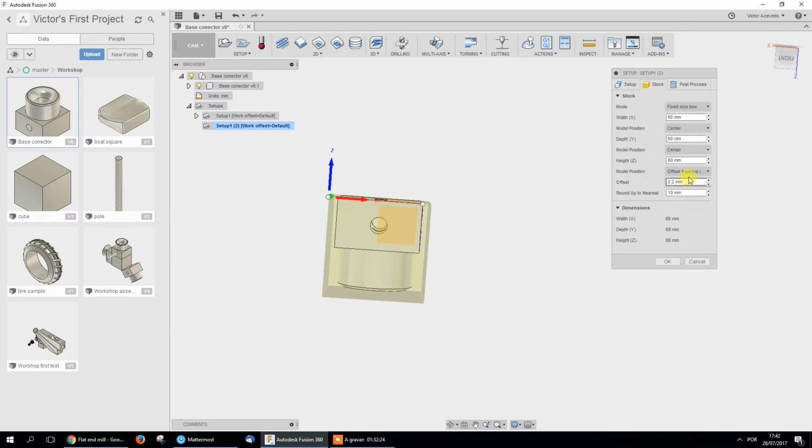Now I have to change the offset Z button to stay with the same material I had previously. Okay, because I flipped the Z, now I need to put 0.2 millimeters on the bottom. We already removed the lock on the vise. Now the vise holds the circle. Okay.